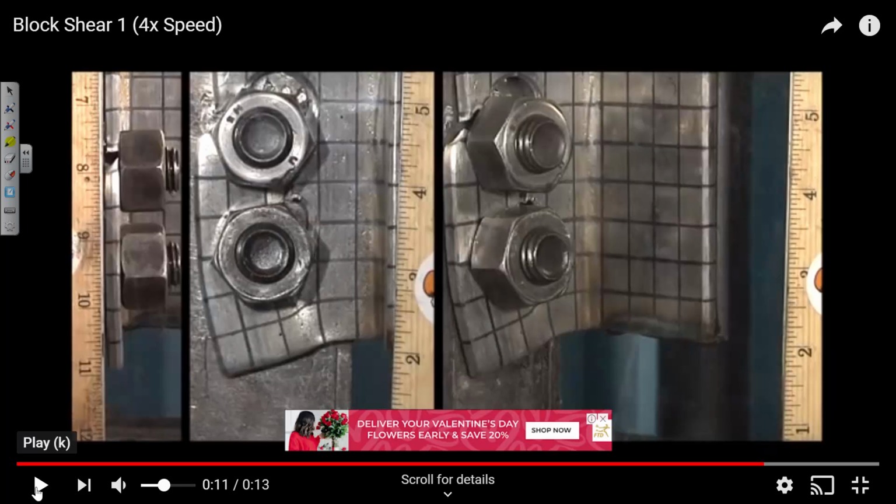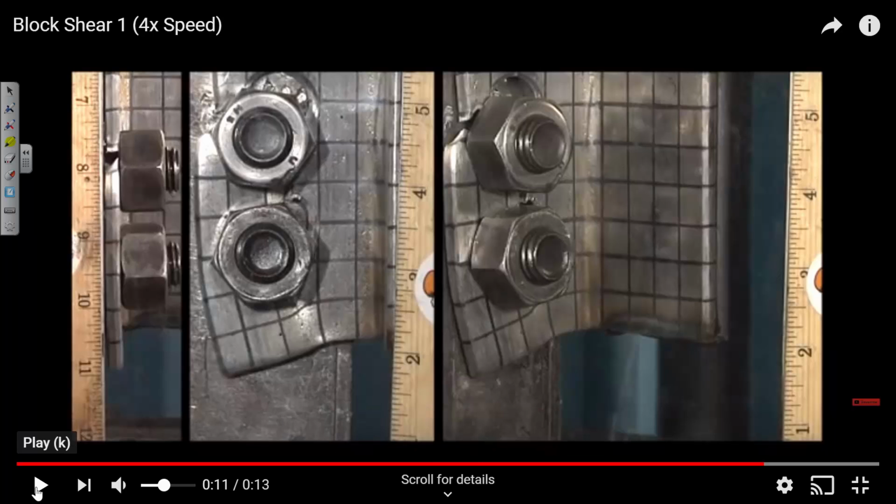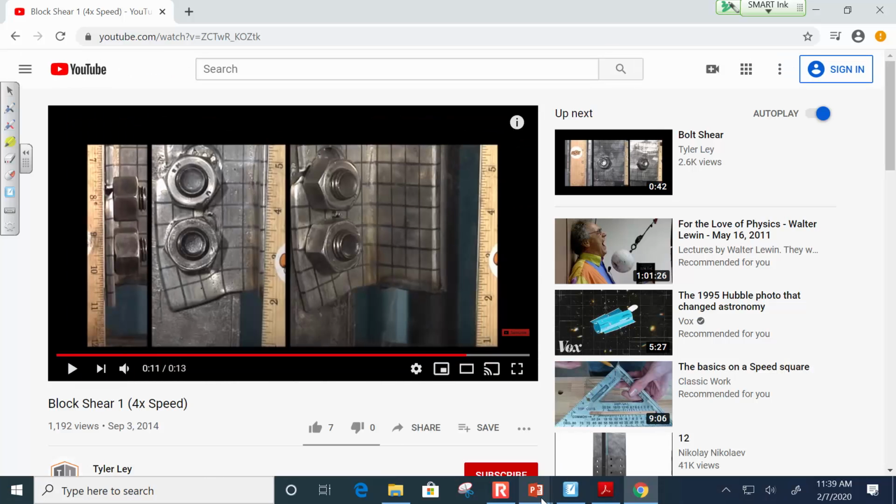What's happening is you're getting a mixed failure phenomenon. I'm yanking on it, and so this chunk right there rips out. From a mechanics perspective, if I'm yanking on it, this right here is experiencing tension, okay? But this is experiencing shear, because you're yanking on it this way, and this is wanting to sit still, the angle's wanting to move, so that path is seeing shear. Does that make sense? So it's not as simple as just an area times Fy. There's a lot more going on, okay?